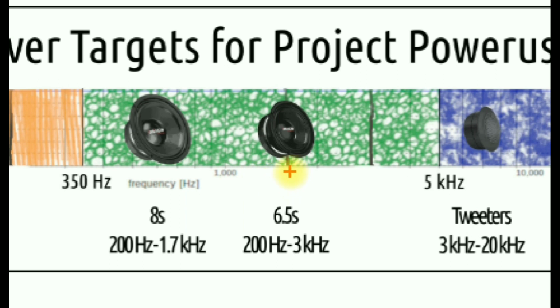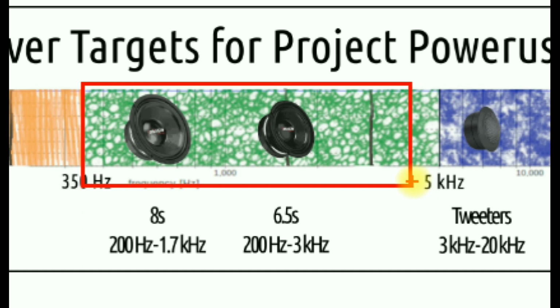is, this one actually is not an acoustic crossover target. The reason for that is because we have this entire section of 200 Hertz to 3 kilohertz.